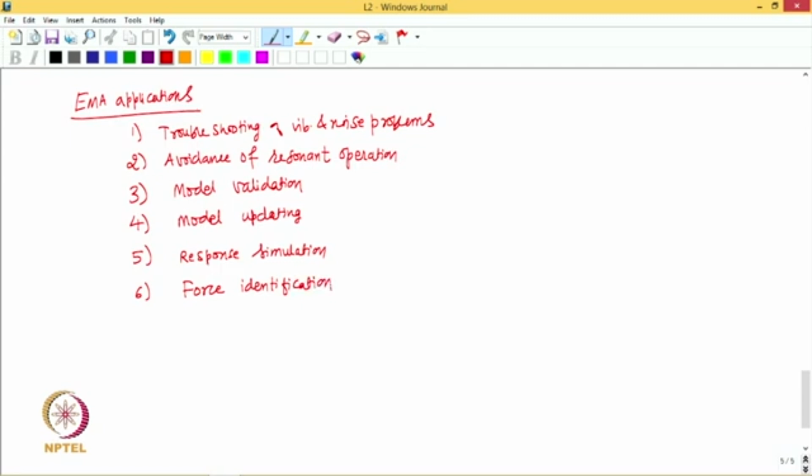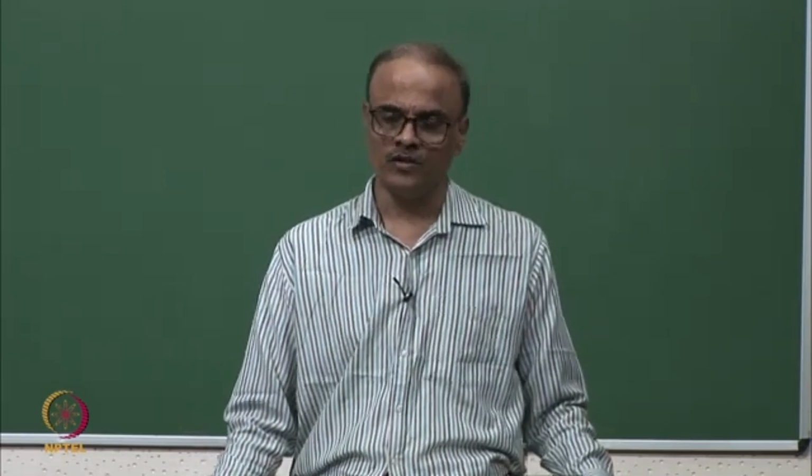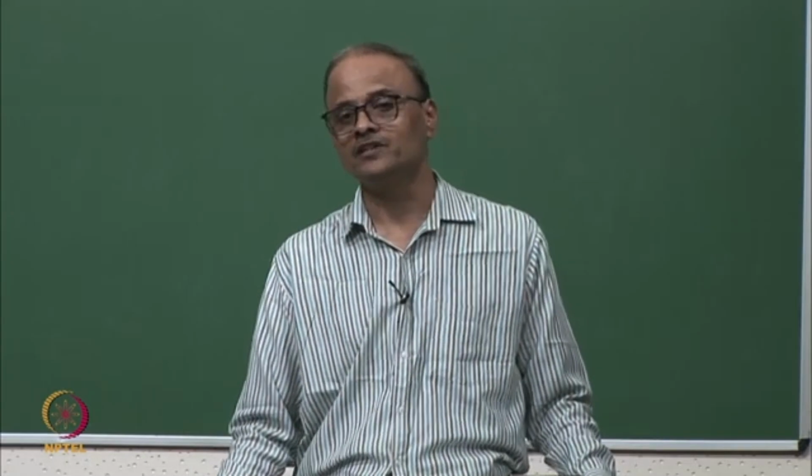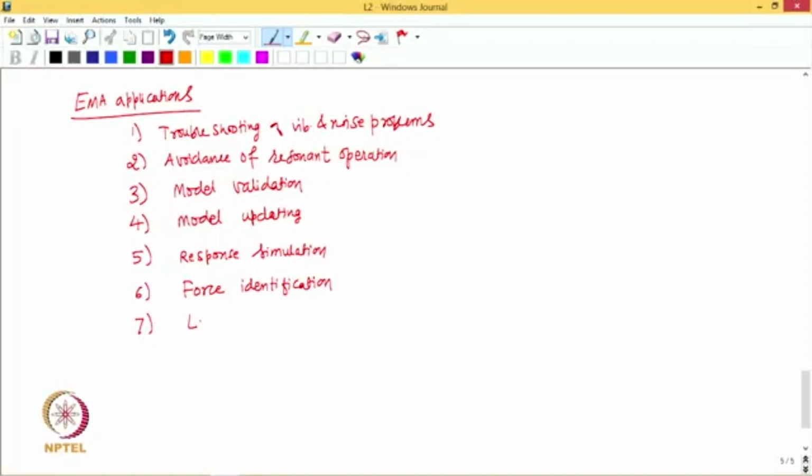Force identification. If we wish to determine what dynamic forces are acting on the structure, the operational forces, then by measuring frequency response functions or impulse response functions and measuring the operational response of the structure, it is possible to determine, again through an inverse procedure, the forces that are causing these responses. These are basically called force identification methods. It can also be used for local structural modification studies.